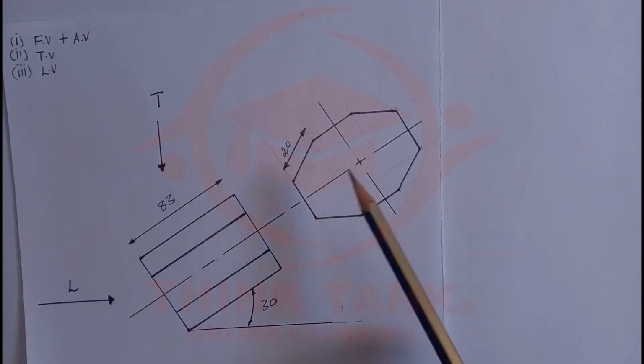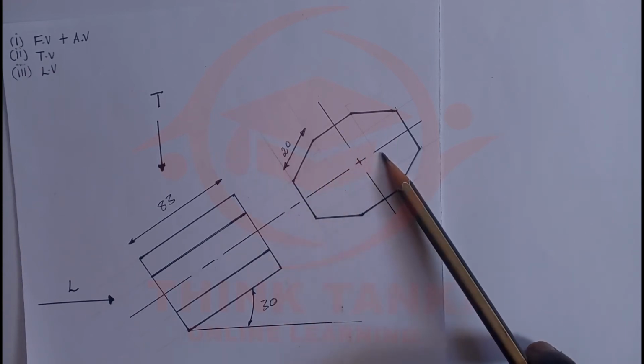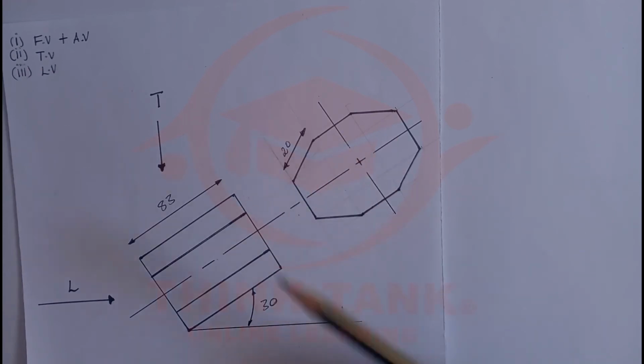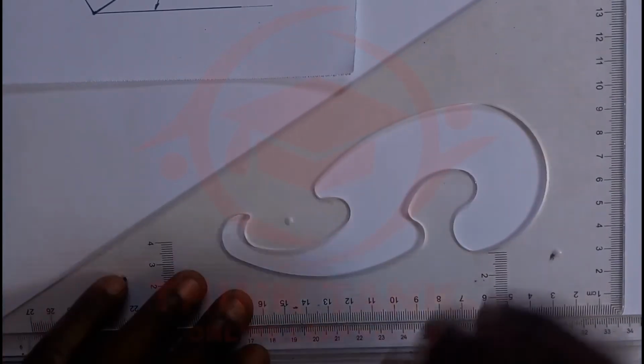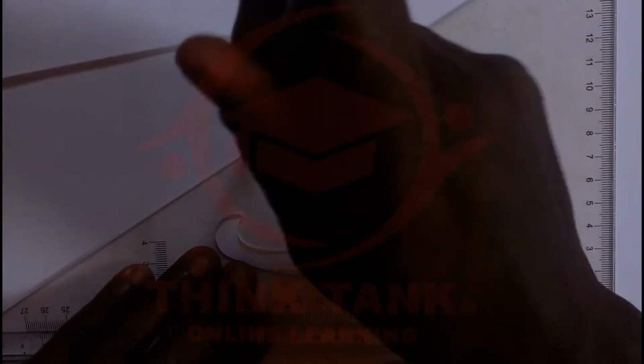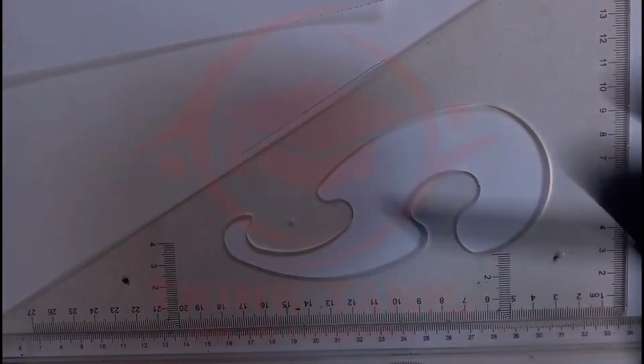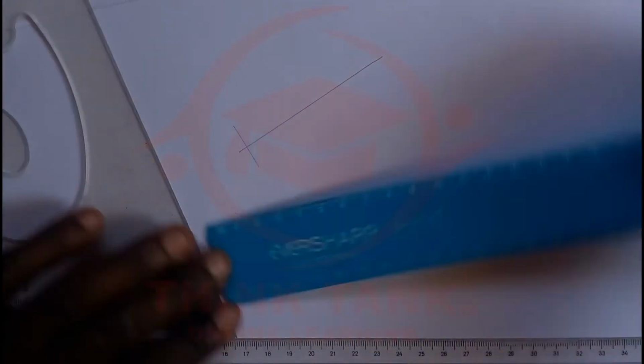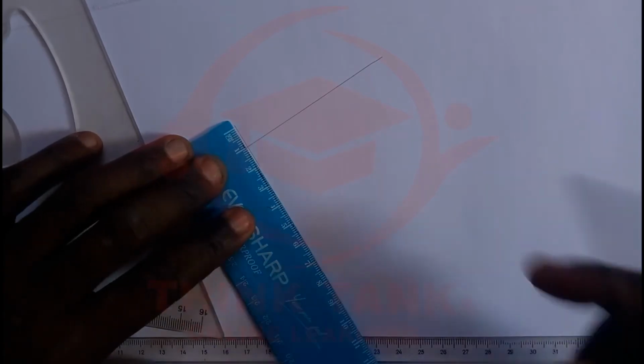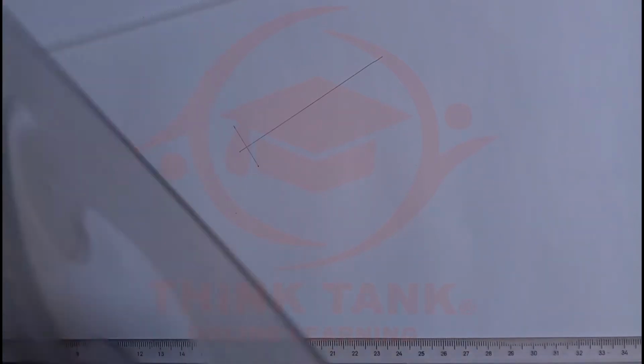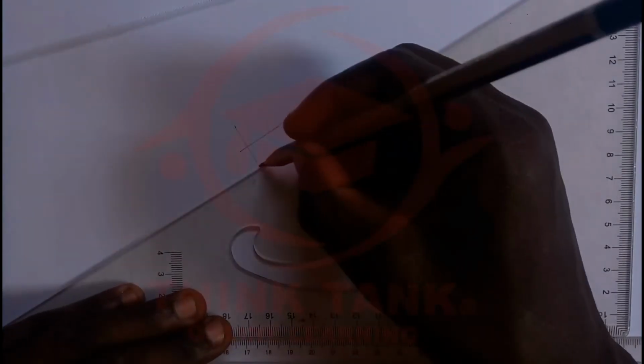The first thing we start to draw is the auxiliary view. You can see this one is the plan. Since our shape is inclined at an angle of 30 degrees, we're going to take a 30 degree set square and draw this line. Come here at a 60 degree angle and draw this one. This is the line which is perpendicular to this. Since the length of one side is 10, the total is 20, so I'm going to measure 10 on each side. Then taking a 30 degree set square, I'm going to project